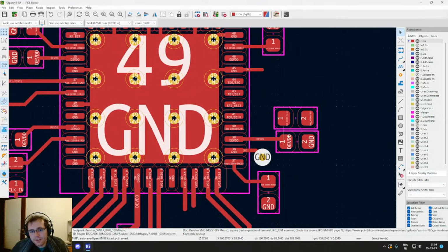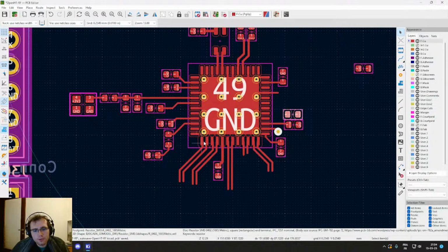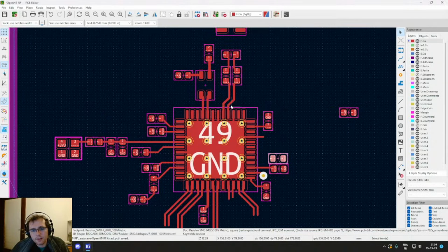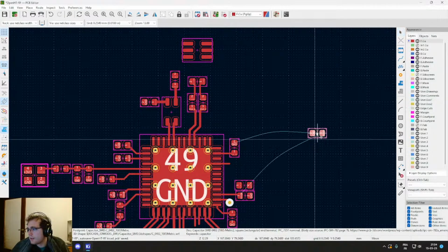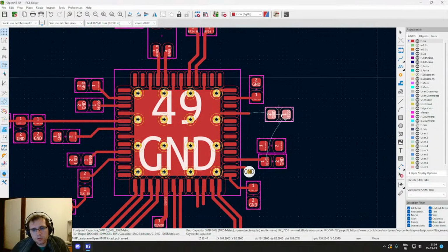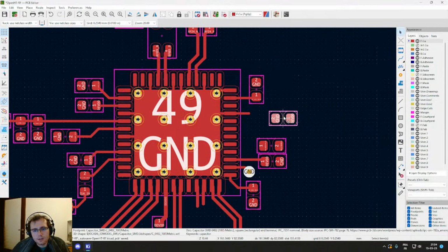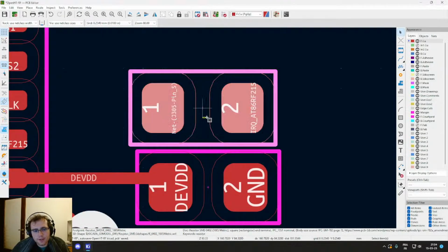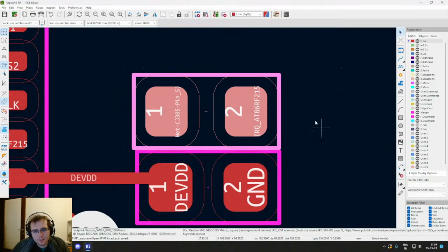Yeah, some components are misaligned, but sometimes when you really want to densify the design, you cannot rely on the grid, because you either have to pick a grid which is too fine, which is a bit weird, or you have to use the control key, and then you don't have magnetism on the grid. So you can misalign things by just a little bit, just enough to be annoying, like this.